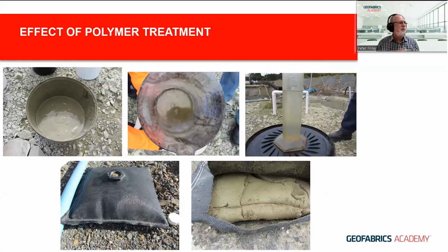So here's a little example of this for a job I did in New Zealand, a bit of testing. So it was taking a sediment from the quarry sediment pond, adding the flocculent, getting good separation and good strong floc, putting it through the geotube or the GDT, a good filtrate, leaving that to sit out and dry out for several weeks, and then coming through and having a look at it and doing a dry solids test on that.